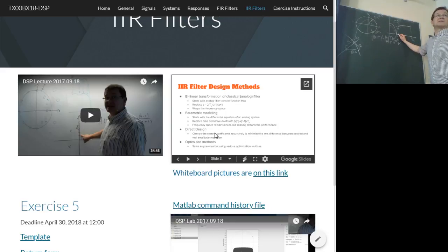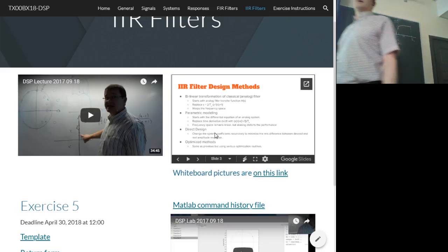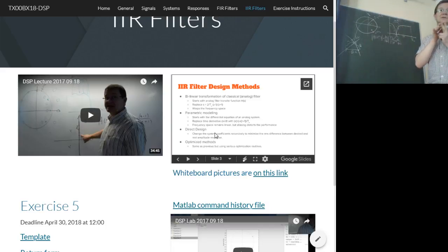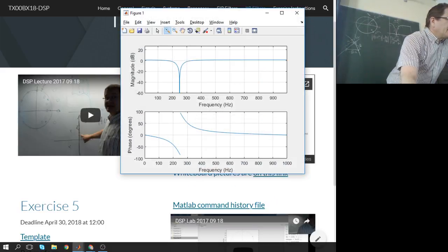And where to use it? If you have a small microcontroller system which doesn't have much computing power, you can still filter out 100 hertz or, say, the third harmonic, which are the most common noise signals on small microcontroller systems which are sampling something. One warning though, let's take a look at this one.